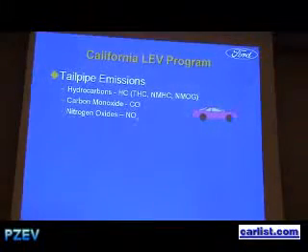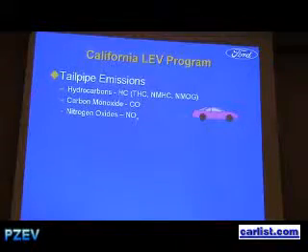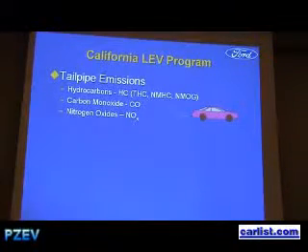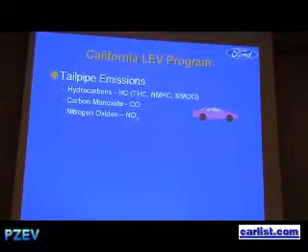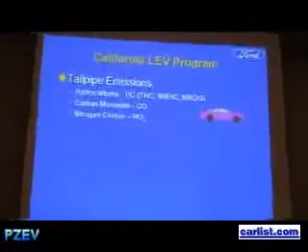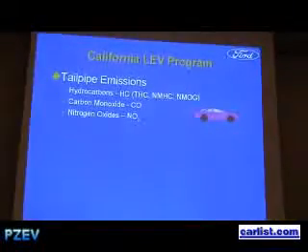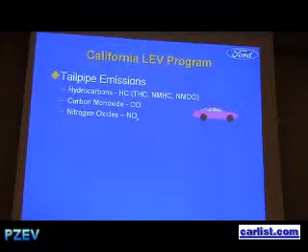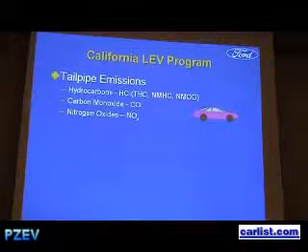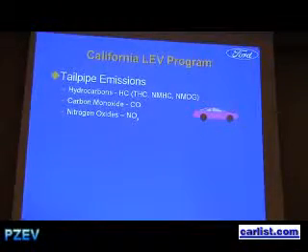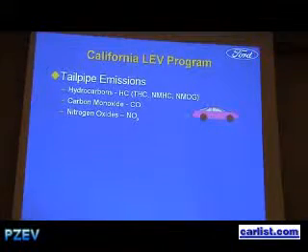Well, it addresses three aspects. The first thing it addresses is tailpipe emissions, and there are three primary emissions we talk about. Hydrocarbons, unburned fuel. Sometimes they talk about THC, total hydrocarbon, or non-methane. Methane is not that reactive, so sometimes they remove that. And there's this thing that California likes, they call NMOG. It stands for non-methane organic gas. It's essentially non-methane hydrocarbons plus other organic emissions like aldehydes, etc.